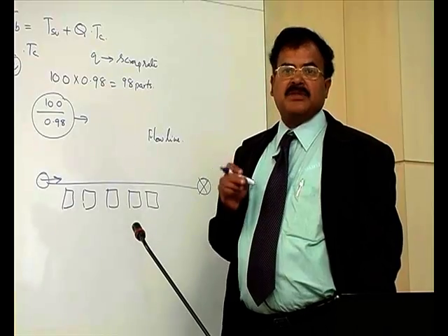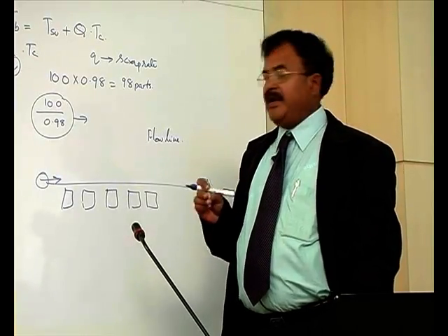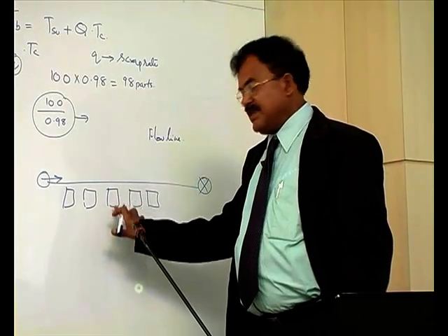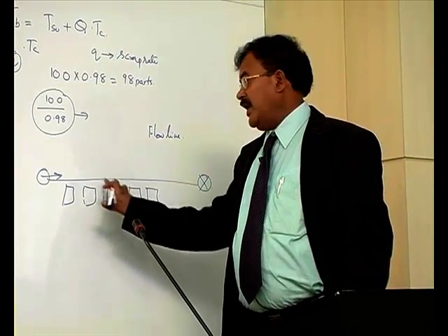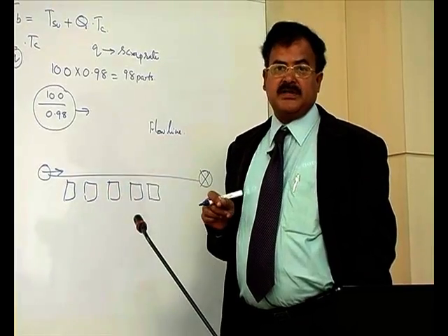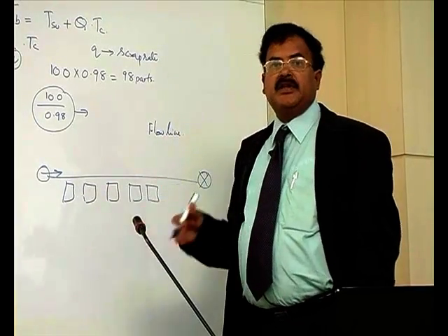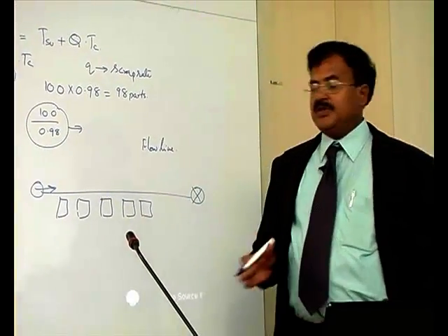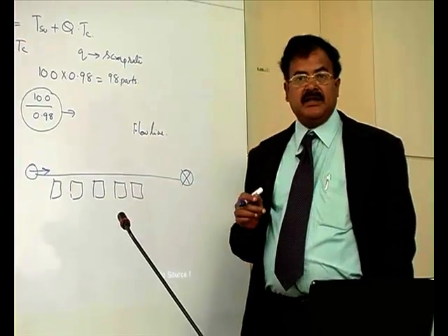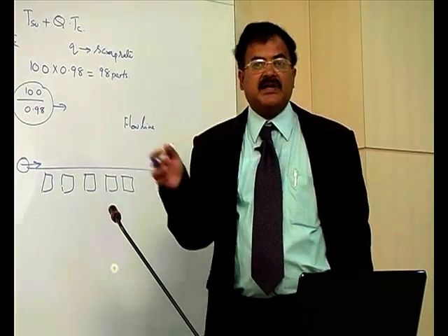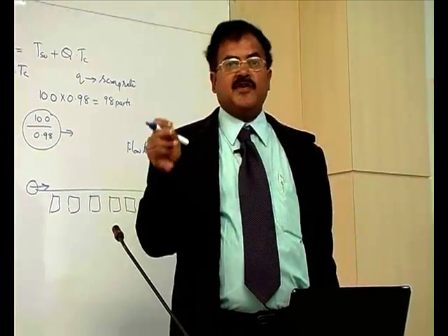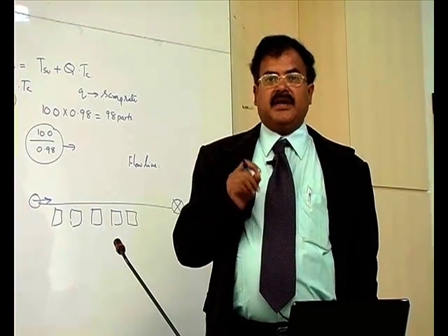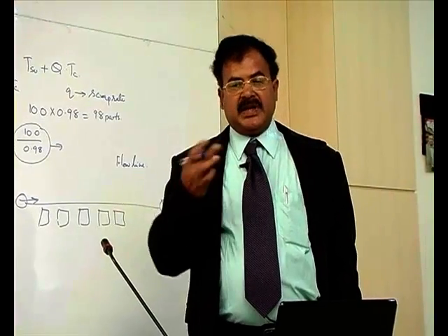If scrap comes, it should be caught at various inspection or level inspection stations used here, and those will remove those parts. The yield will be reduced. The yield of the line is reduced. Total line yield, let us say it is 100%. It won't be 100% if you allow scrap there. That means it is going to be around 90% or 95% like that.